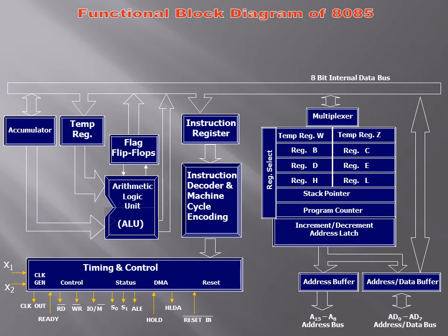And we have the reset signal as RESET IN, a signal which will reset the microprocessor's internal chip, and then RESET OUT, if the outside device is to be reset by the microprocessor. If it wants at any place to synchronize with the outside device, it gives a reset out signal. Then we have the different controls which are generated by the timing and control section, and they are internally connected to the various devices inside the chip.